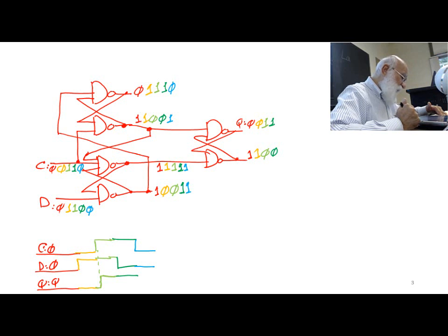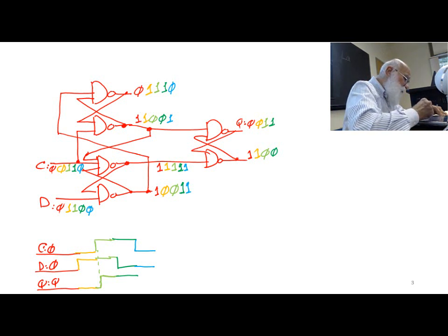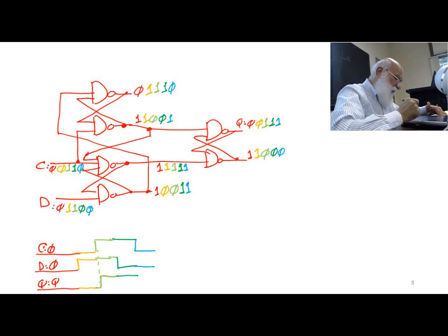All right, so what do I have here? I have 1, 1 on the inputs of the cross-coupled NAND structure of the output. And let's analyze the top gate. There is a 1 there, and then there is a 0, which is the lower gate, and therefore the output remains 1. A 1 on the lower gate and a 1 on the lower gate, the output is 0. So what it means is the output really did not change. Okay?